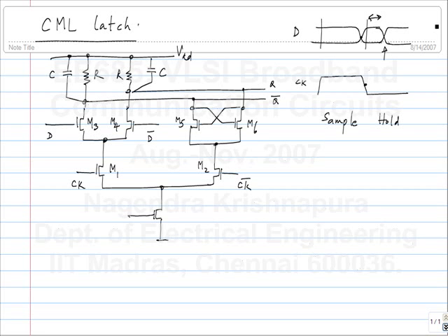Is this the hold time? When the clock is high? What is the hold time? After the clock becomes low or high? No, here, see, when the clock is high, the input is directly affecting the output. And when clock is low, that is the hold phase. Okay, so where is the hold time? After the clock becomes low. So the amount of time for which data has to be held constant after the clock becomes low. That is right. Okay. And what is the setup time? Before the clock rises.